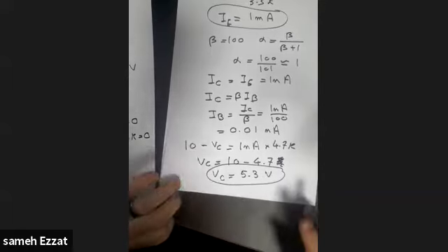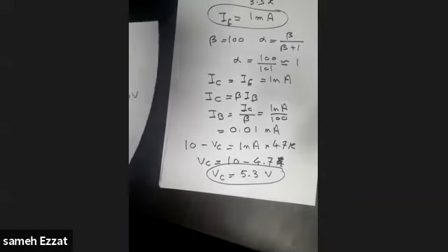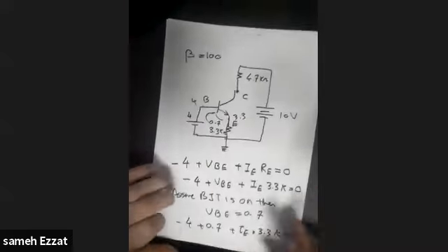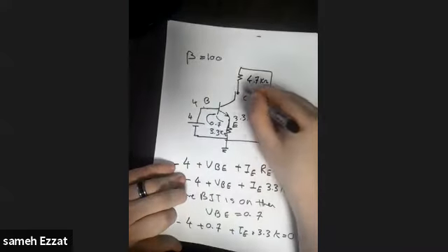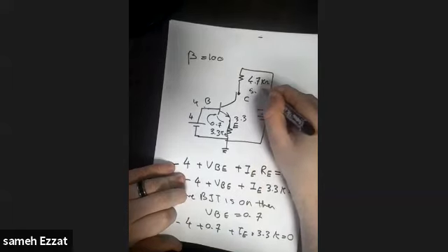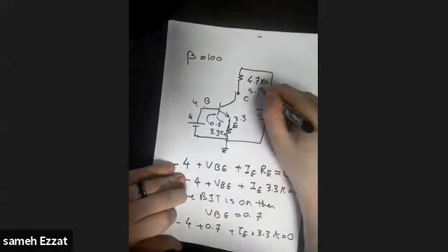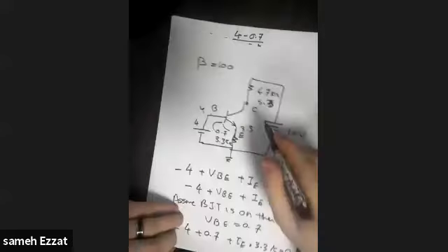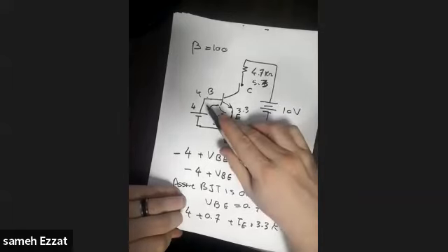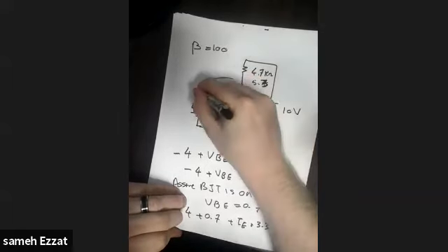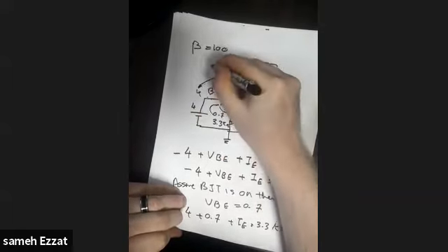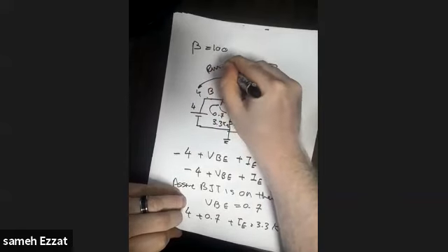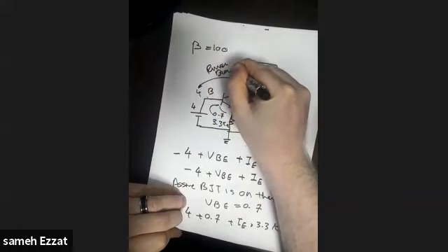This is very, very important that you stop, wait, and think. The voltage here is 4. The voltage here is 5.3. Yeah, so this is 5.3 and this is 4. So now we are right. This is a reverse biased junction.